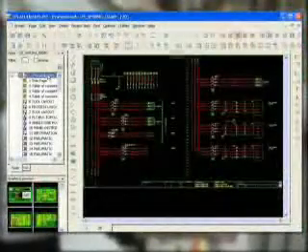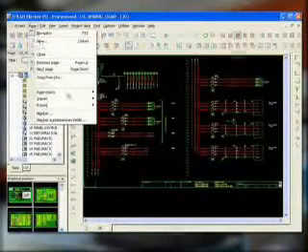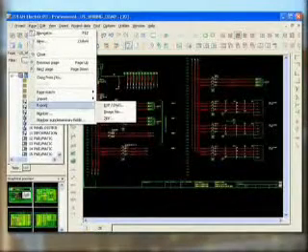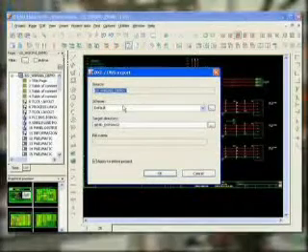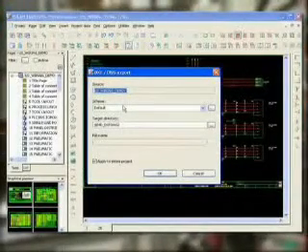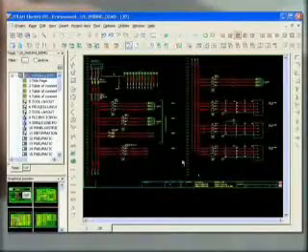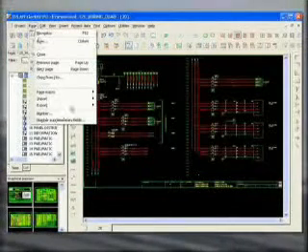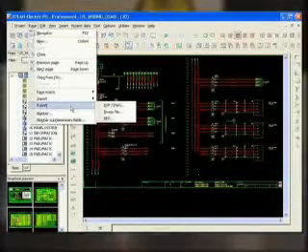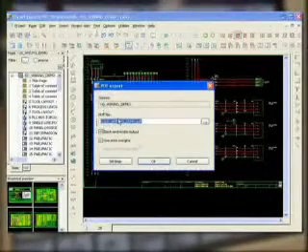There are several export options available in Eplan Electric P8, one of which is the DXF DWG export. To do this, select Page, Export DXF DWG. Another export method is PDF. To generate the PDF, select Page, Export PDF.